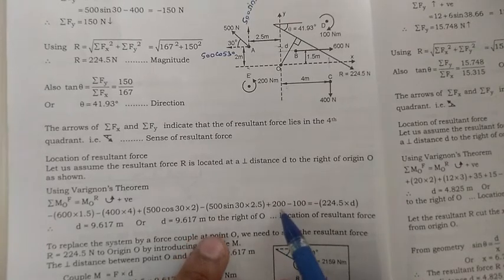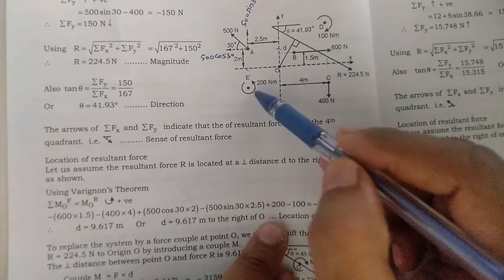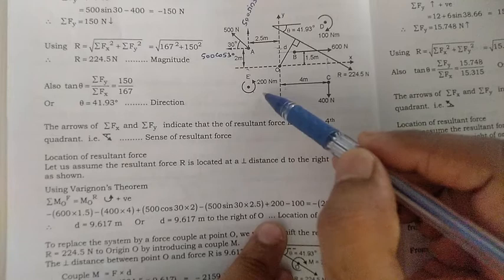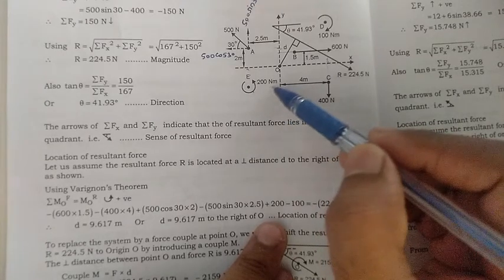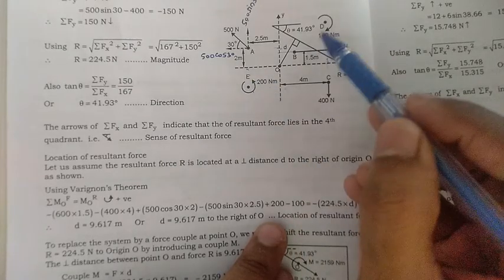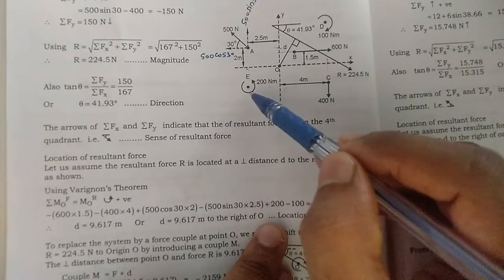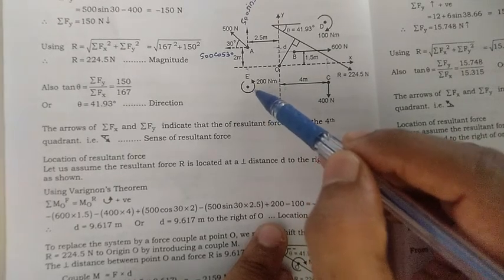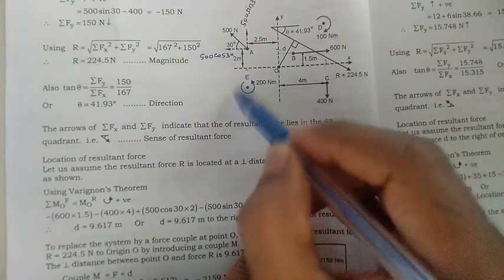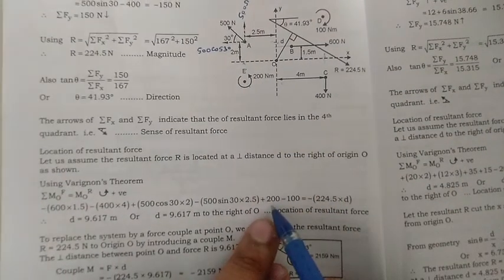Now the next force. An important thing here: whenever we find any force in the problem that includes the Newton meter unit, and if that is represented by a couple sign, then it is not necessary to multiply by any distance for that couple. Pick up the value as it is. So see the direction of the rotation. This turns about this particular point in anti-clockwise direction. So for anti-clockwise direction, just consider the positive sign. Don't multiply by any distance for this one.